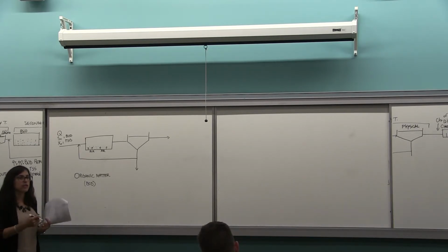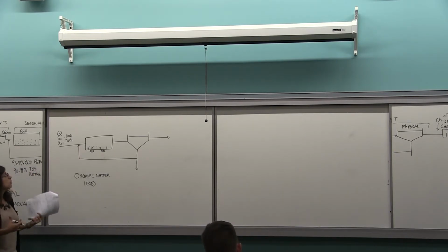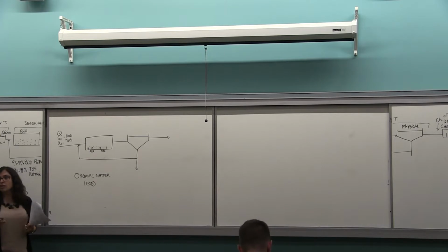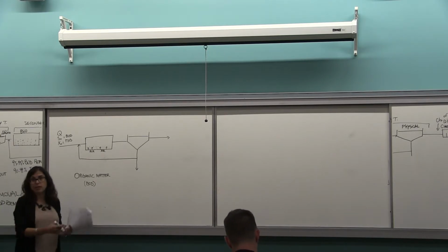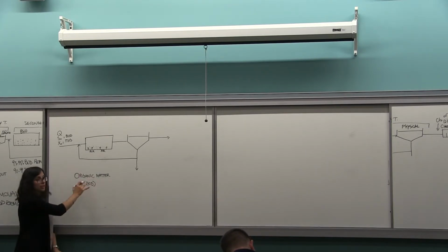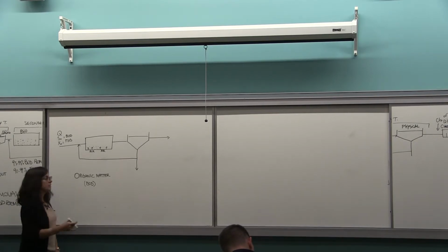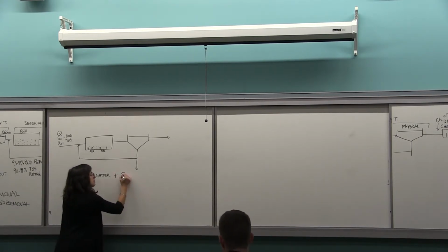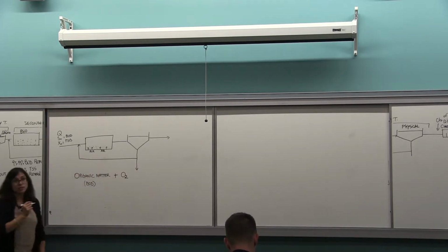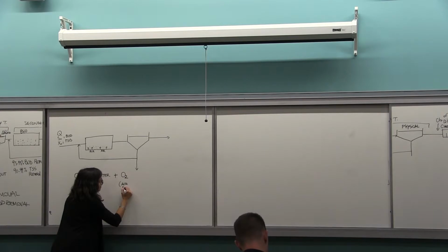Instead of measuring how much sugar there is, how much protein there is, we measure the oxygen that will be needed to oxidize that organic matter. So the organic matter can be expressed in milligram of oxygen per liter. That's oxygen in air, so air provided.